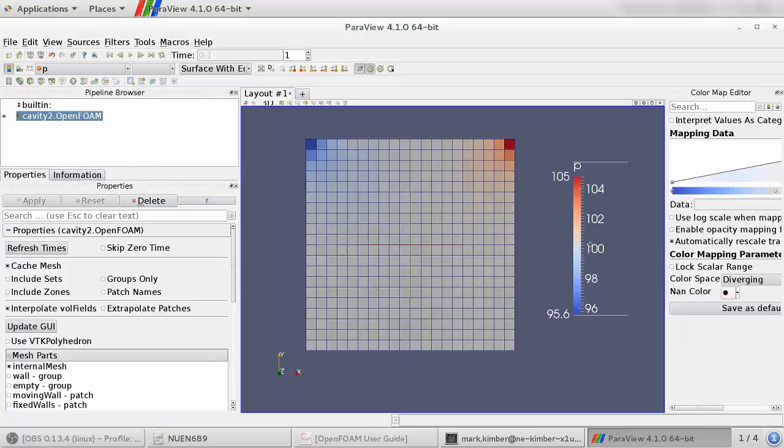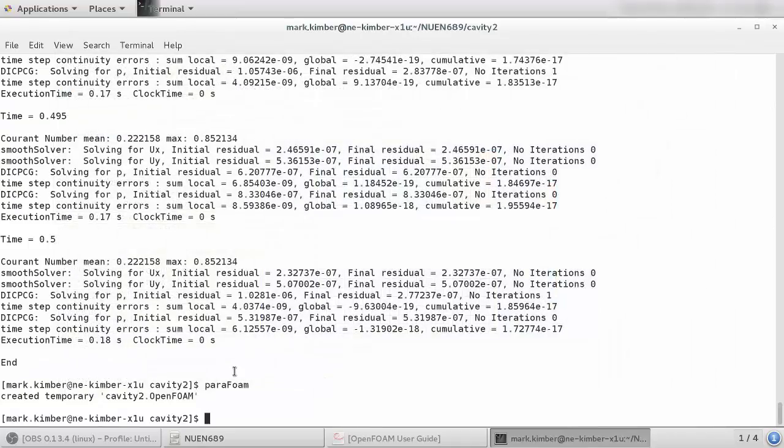But if we take one of those cells and replace its equation, forcing it to have some temperature, then it pins down the rest of the field inside the flow. So the same thing is happening here with pressure. And if we had a compressible solver, then we wouldn't have this option, because the absolute value of pressure is also important.